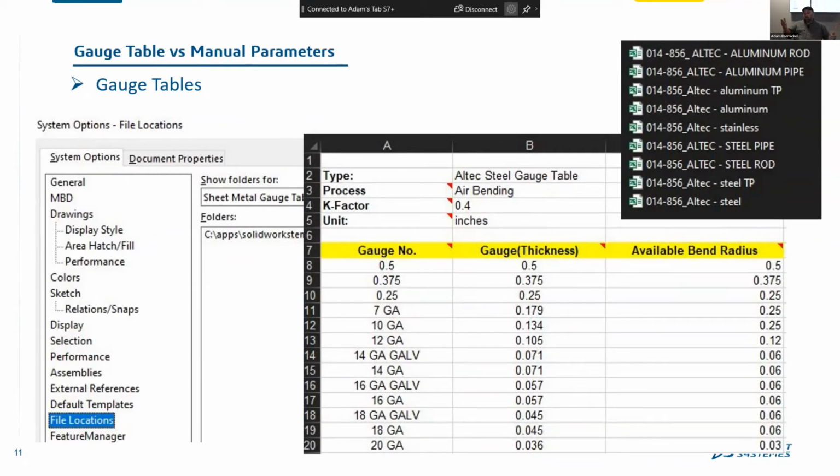You want to make sure that's taken care of. But then also, like Tank was saying, you can set that bend radius on the press brake. If you're using a press brake, what die are they using? Is it a 1/4 inch die, a 1/2 inch die, an 1/8 inch die, a 16th inch die? Set that up according to which material it applies to, and then you don't have to worry about it. When you create the sheet metal table, it'll populate that when you select it.